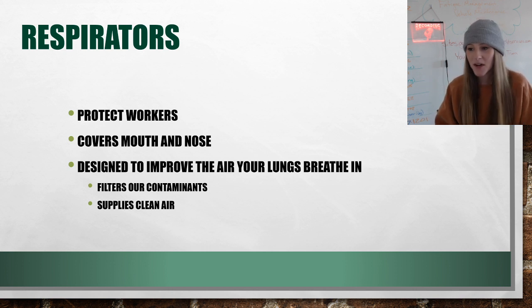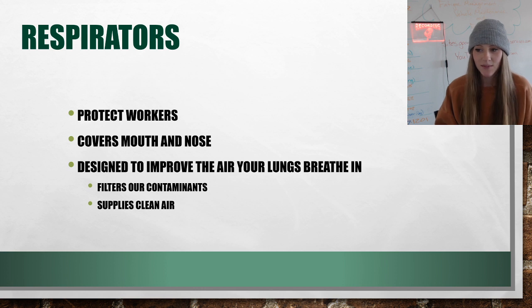They are to protect workers. Inhalation is one of the 4 main ways you guys can be exposed to hazardous substances. So if engineering and administrative controls can't keep you safe from inhaling contaminated air, you must wear respiratory protection. They protect you from breathing in dangerous substances when you're working in hazardous environments, cover your nose and mouth, and improve the air your lungs breathe in by filtering out contaminants or supplying clean air from an outside source.